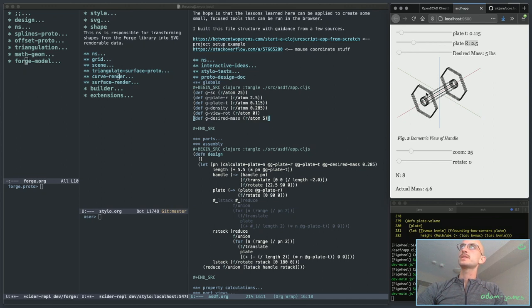Physical design improvements. This hex plate itself, if I'm welding them together, it might make sense to have on every other face a little notch cut in. That way you can align the plates, pinch them in a vise, and then do a weld through the groove. Then it should be all together, and you just weld through each of the 3 grooves, and it should be good enough. Then you have 2 blocks, and then you just weld them to the ends of the handles on a flat so that the hexes aren't misaligned.